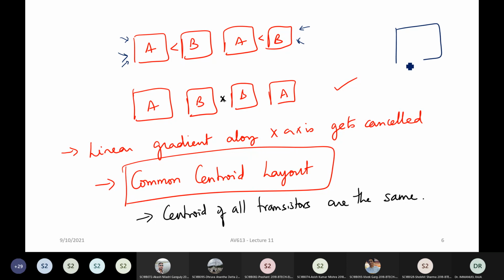If you look at a transistor under a SEM or a TEM, that is a scanning electron microscope image or a transmission electron microscope image, you will see that you are not going to have very sharp, clean-cut lines. You will have some jaggedness. But especially these edge devices will have more jaggedness, because that is where the polishing hits. That can impact your current a little bit, because now your width and other things are getting affected.